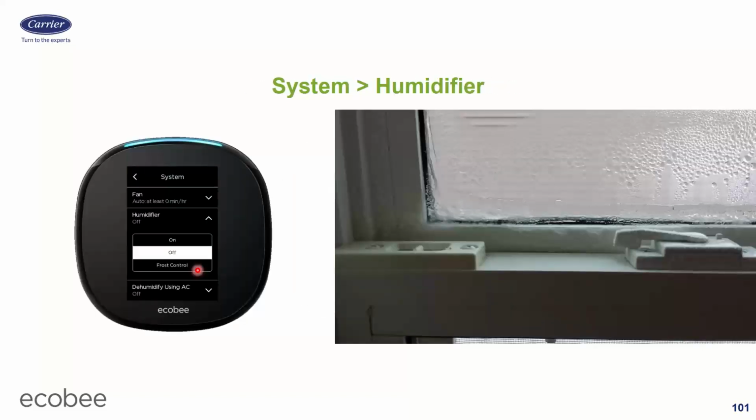We talked about that last week when we were talking about adding a humidifier, and we told it on the install screens how good the window was. Remember, we had the setting from 1 to 7 on how good the window is, right? 1 meaning it's a really, really crappy window, 7 meaning it's a phenomenal window. So when you put it on frost control, it'll then use those settings 1 through 7.